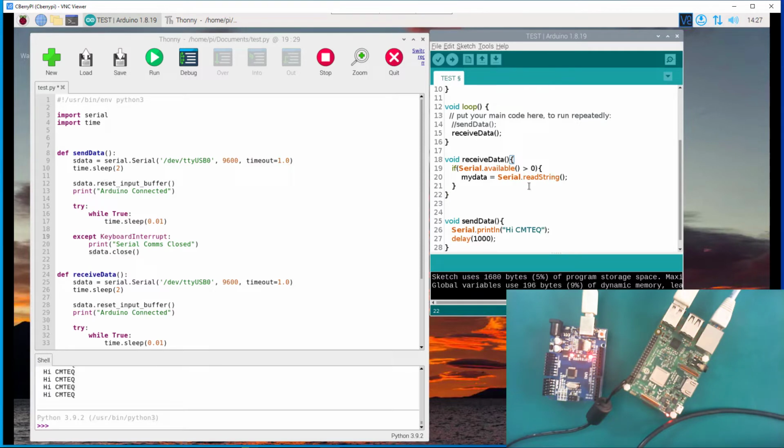So you can just change it by replacing it with a similar function. So that is serial read string until. Then you need to pass a parameter into the until. Basically you're going to tell it to read string until it receives something. So it should also be a character. You can just say it must read until it receives a new line symbol.